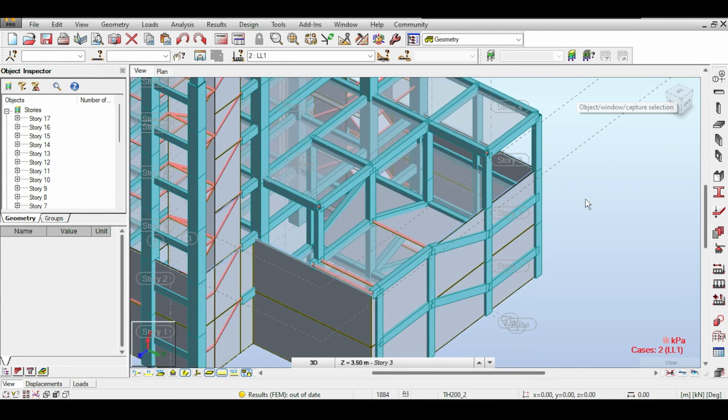Although in real life, I would immediately go to the architect, talk to him, and explain that he should change or increase the size of the ramp or find a solution for that. The solution I have done is I tried my best to somehow fit in a ramp here. In this case, I have made the car go to the right, go counterclockwise, and be able to go below the ramp. And this is how I would do it. Of course, you can enter the story from this side. So I think this is as good as it gets.